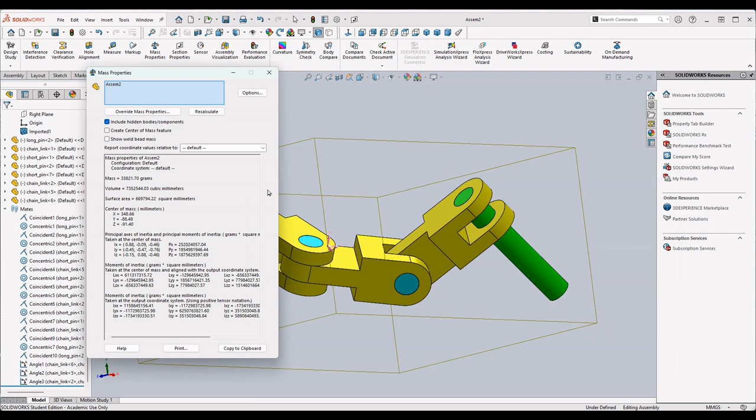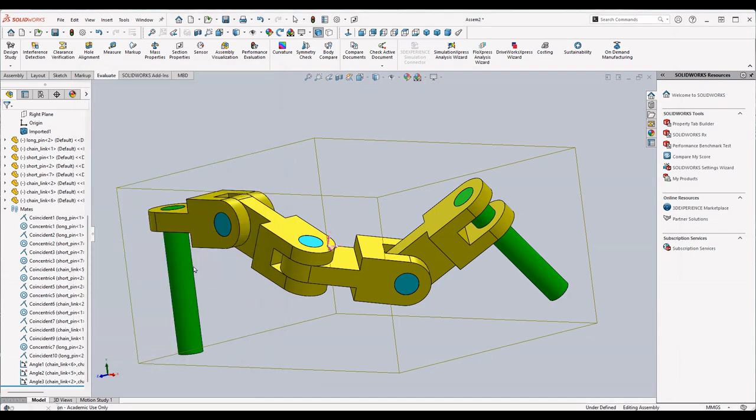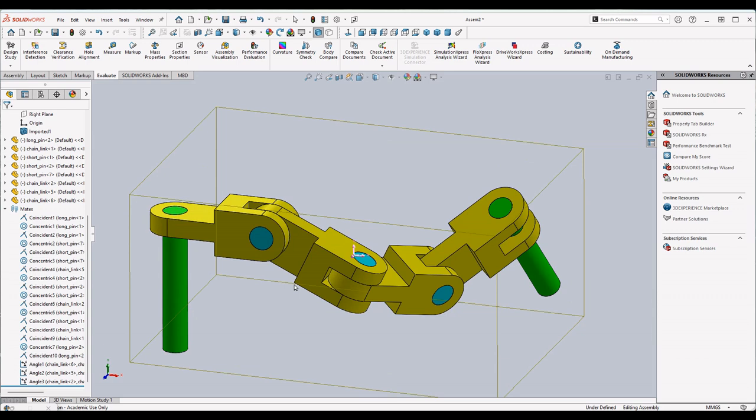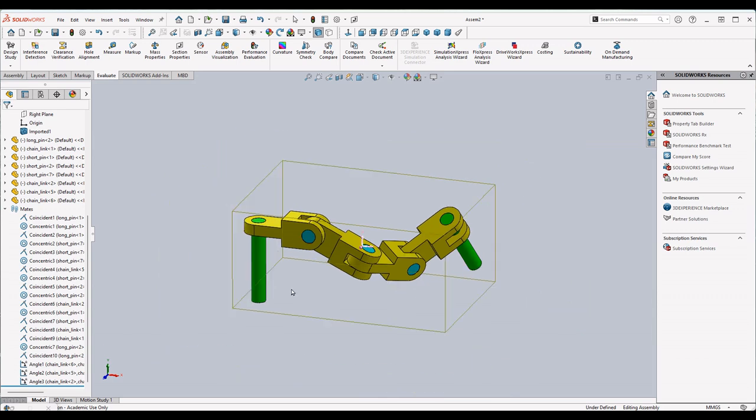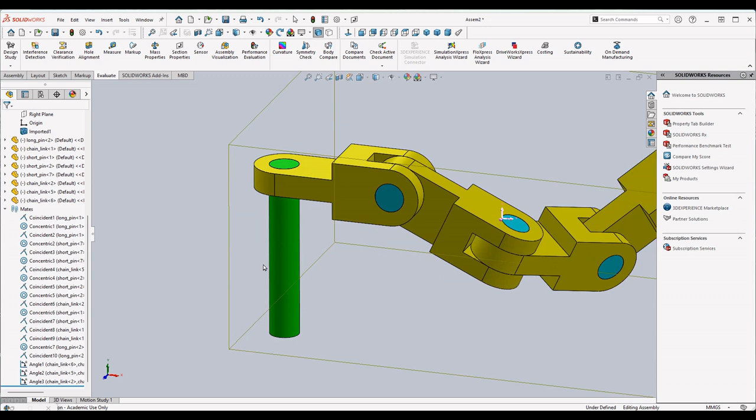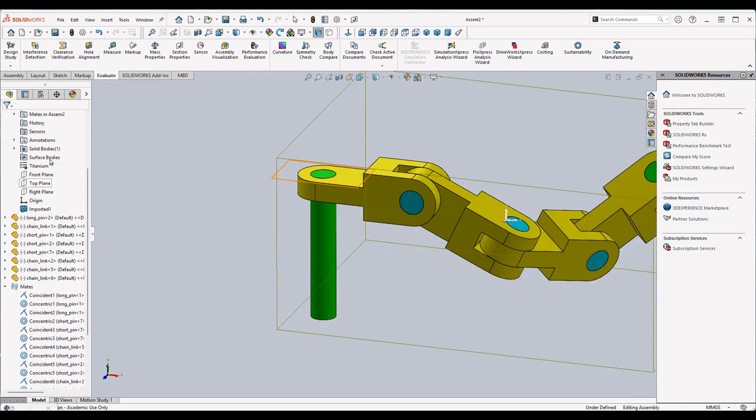So my advice, as always, is just do it right the first time, right? If you do it in a systematic way that you know it's going to work, then you're going to succeed more. What I did differently than at the beginning of this video is I started by paying super close attention to where that origin was and making sure things were oriented correctly right off the bat, which I confirmed by making sure the center of mass is calculated from the origin of the assembly.